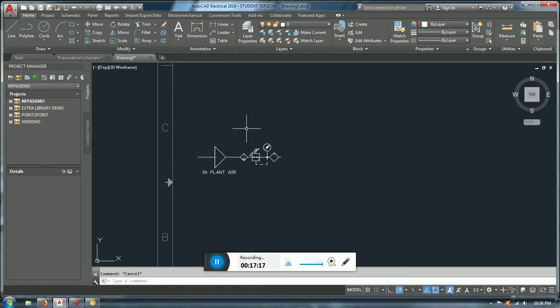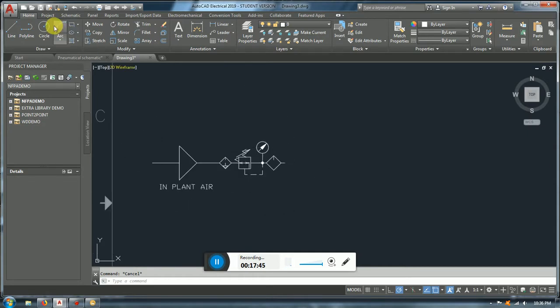So now we have the most basic part of a pneumatic diagram. You're always gonna need that. If you don't put it, it's because you assume, or you're gonna design a part that already has this in another part of the machine. So you're just making a complex assembly with pneumatic systems, but that is going to be connected to the machine. Then, of course, the machine has this FRL, as they call, filter regulator lubricator, so you don't have to make it. But if you're going to do the entire machine, yes, somewhere you have to draw that. So this is the most basic part of one of those pneumatic assemblies.